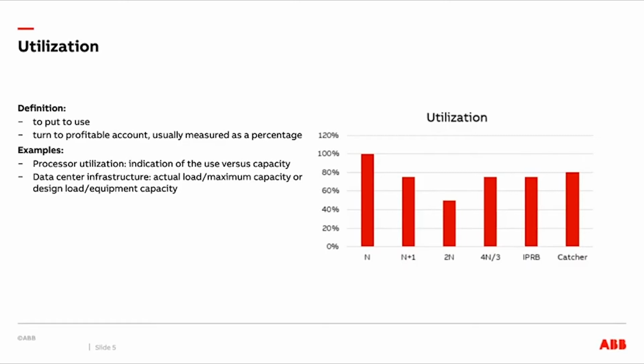A system with redundant components, defined as an N+1 system, increases reliability and cost but lowers utilization. A 2N system, also called a system plus system, provides redundant paths which significantly increases reliability, but also increases cost and reduces utilization. With a 2N system, there are two independent paths which share load, so the maximum design utilization is 50%.